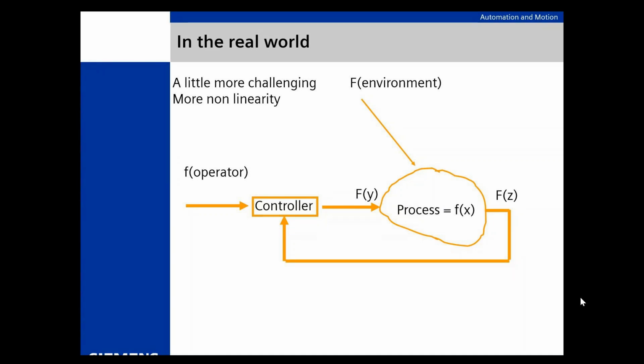Mathematically, the controller has to deal with that. Okay? And if it can't deal with that, it's going to be unstable. You're going to have a loop that's bouncing around and chasing itself. Okay? What that means is, in the real world, there is inherent deadband in the system. Sorry, that's just the way it is. It's a law of physics. There's no way around that. Be it little, be it a lot, it's there. And part of what the controller is dealing with is that deadband. And we're going to talk about what happens when it can't deal with that deadband.